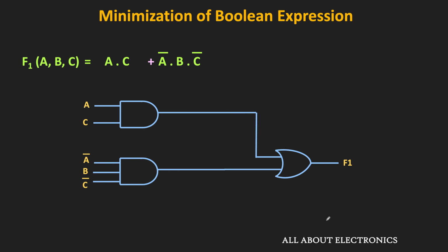So of course, as we have seen so far, using the Boolean laws, we can definitely minimize the Boolean expression. But to minimize the expression algebraically, we need the familiarity with the Boolean laws. And as the number of variables increases, it becomes difficult to minimize the expression algebraically. And after the minimization, we are not sure whether the reduced expression is actually minimal or not. So in such a case, this Karnaugh map is a relatively simple method for simplifying the Boolean expression.